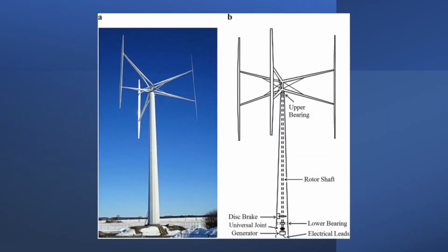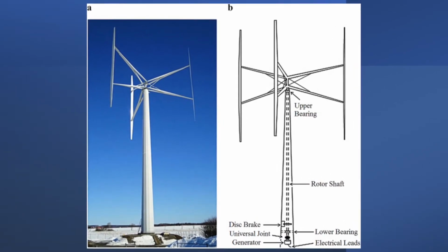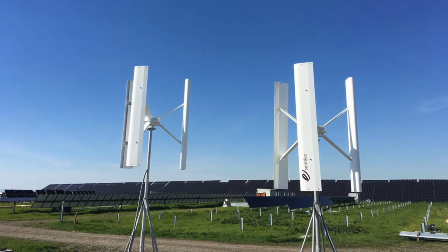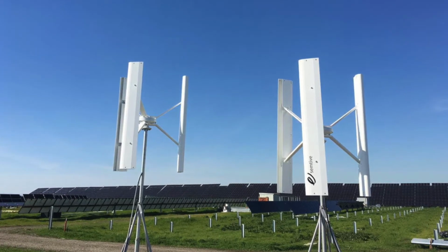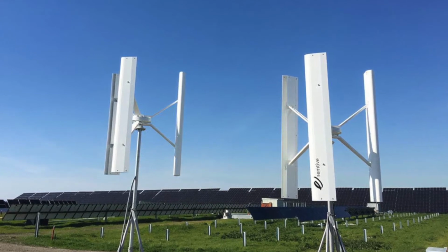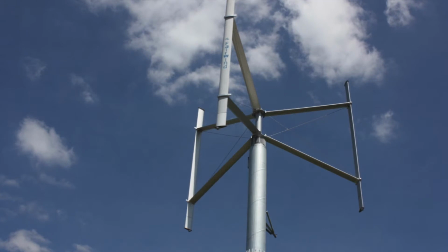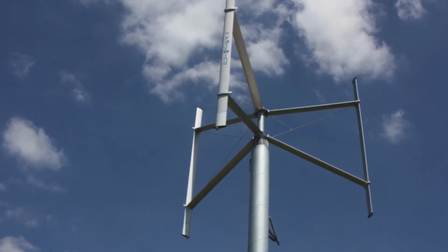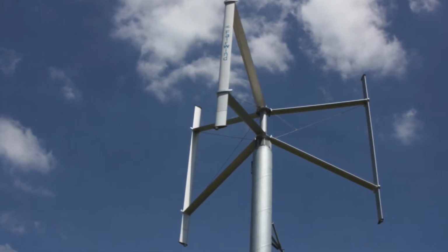Vertical axis wind turbines have their rotating axis normal to the ground. They can be placed on rooftops or on the ground and can collect the wind energy from all directions. They are also much more compact and take up less space than a horizontal axis turbine. They are mainly used at slower wind speeds and lower altitudes, where less wind energy is available. Due to the location of the rotating axis, the generator can be simply placed at the ground, making them easily accessible.